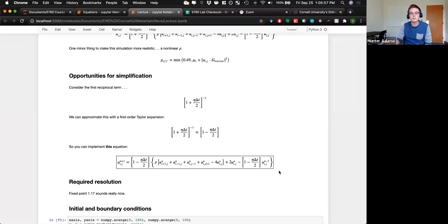So the number of cycles that it will take for you to update a single node is not going to be very many. Depending on the size of your state machine, you may be able to update a single node in like 2 to 5 cycles on the FPGA, 2 to 5 rising edges of the clock 50 line. Also recall that we're producing audio samples at 48 kilohertz.